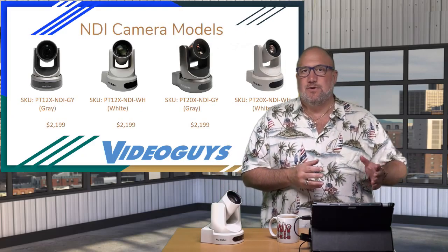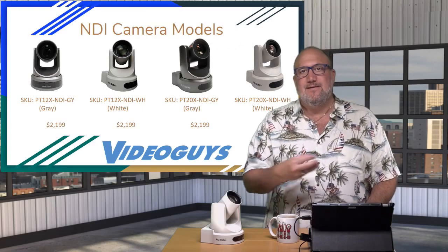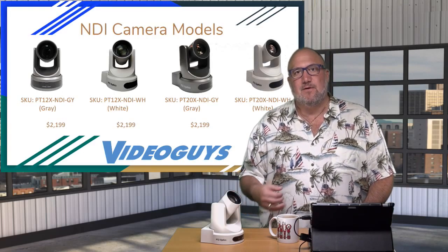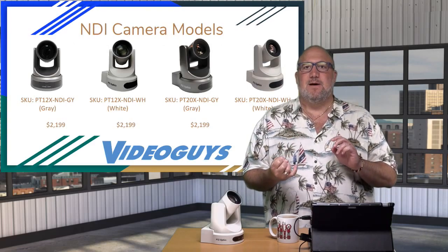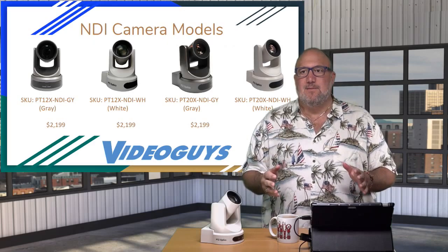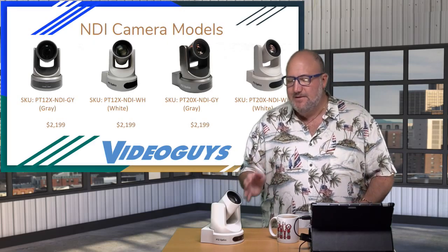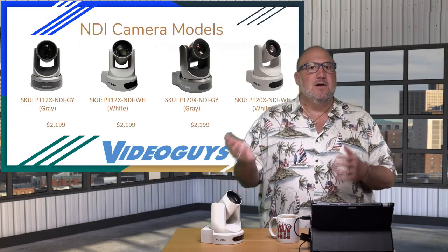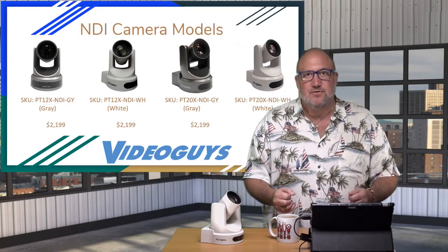These PTZ cameras will connect via NDI, so they're going to send the video signal via NDI to your switcher or mixer, vMix, TriCaster, whatever you're running. It's also going to give you PTZ control of your camera through a single network cable. You don't have to worry about running SDI, you don't have to worry about running HDMI, you don't have to worry about running control cables. Through one basic cable, gigabit Ethernet, you'll be able to connect your PTZ camera, multiple PTZ cameras, control them from your TriCaster or from their NDI-enabled joystick controller, and you'll be good to go.